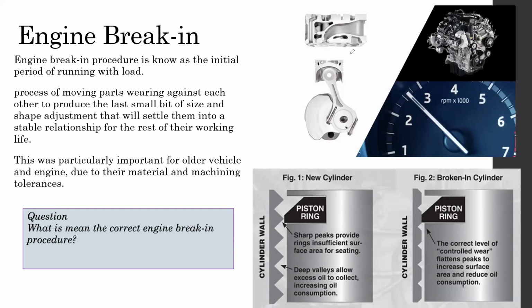When the engine is being rebuilt, I told you that we are doing some machining processes, and one of these is honing. During the honing process, it cuts small grooves on the cylinder itself to retain the engine oil layer on the cylinder wall.